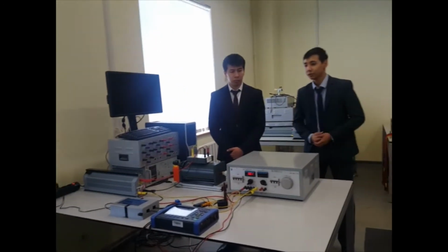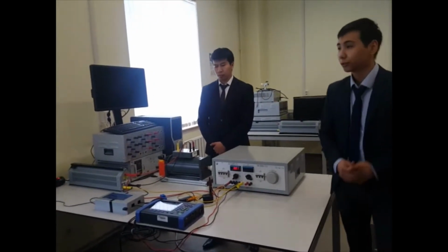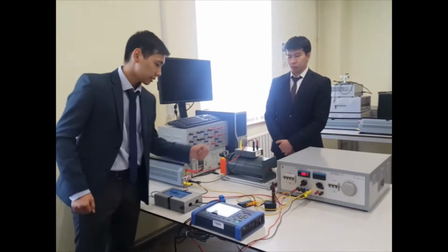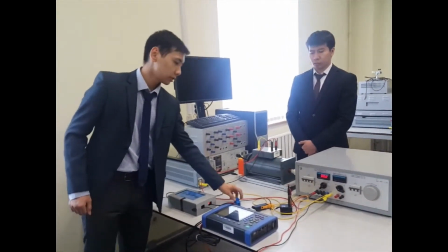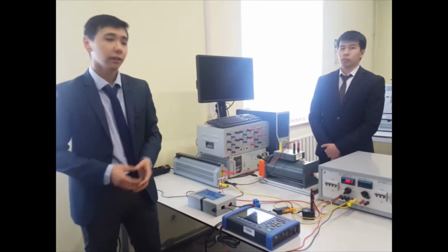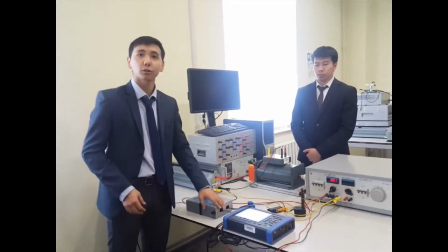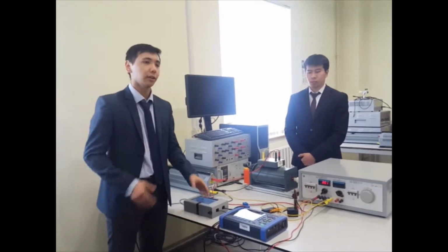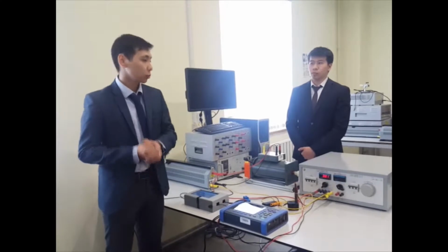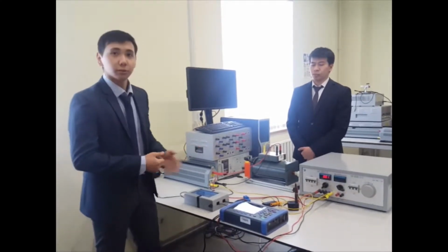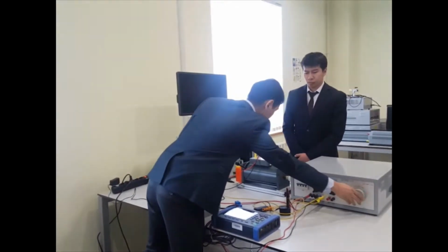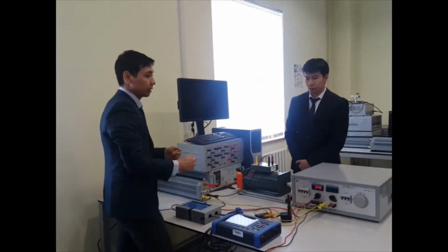Hello, my name is Nur Sultan. Now let me show you more details about our smart meter. First of all, our smart meter has two sensors, a CT and a power adapter, that measure current and voltage. Then this data goes to the microcontroller inside our device, which calculates power, active power, apparent power, and power factor as well.